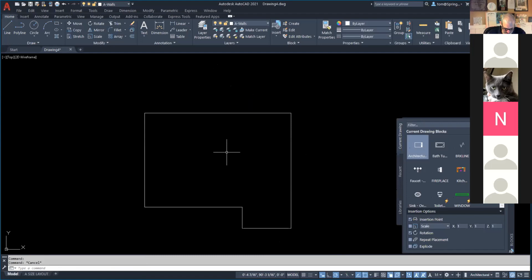Now the chimney, I'll just go ahead and do this because I've got it written down here. So I got 3'2" by 2'6", so that would be 5'8", and then it goes out 2 feet. So I'll go Polyline from here, 5'8", and then out 2 feet, and then it goes down to 4'8", boom, and then back. Okay, so once I've got that, that kind of does that.